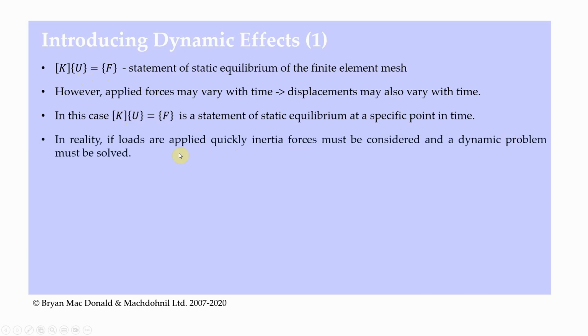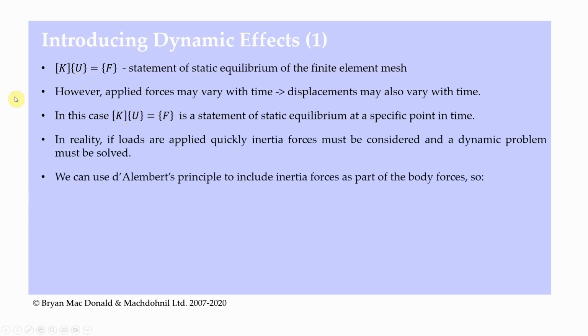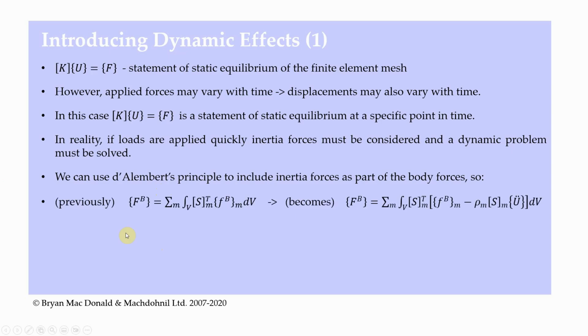In reality, if loads are applied quickly, inertia forces must be considered and a dynamic problem must be solved. We can use D'Alembert's principle to include inertia forces as part of the body forces. If you recall, D'Alembert's principle basically says that an accelerating body can be transformed into an equivalent static system by adding an inertia force in the direction opposite to the motion, which acts through the center of mass. So in our case, we had the body force here, being just the shape function times the applied body force.